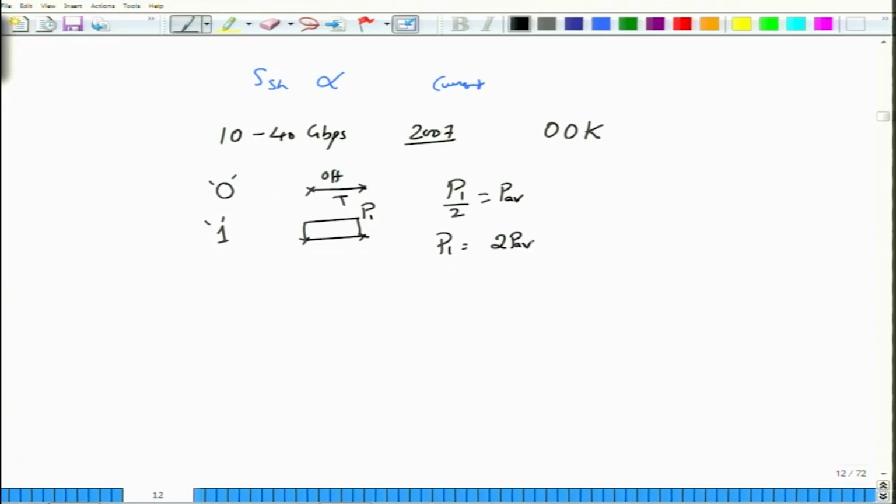So, what you see is that the laser is on to transmit a symbol 1, and the laser is off to transmit a symbol 0. When you send a 0 and put a photodetector to detect and obtain the electrical pulse, over that duration you won't see any photocurrent, because assuming all the other noise sources of the photodetector and the system are 0, then I_PH will be equal to 0. On average you don't get any photon, you don't get any current, because no photons were sent when symbol 0 was transmitted.